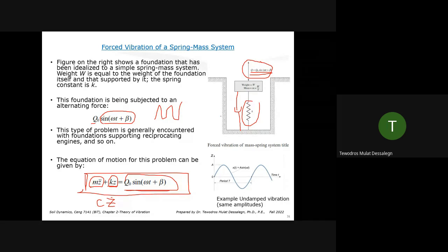In the material assumption, if you assume both damping and stiffness, then you'll have both forces, the damping component and the stiffness component. When you analyze a static problem, it's always the stiffness component, which is K times Z equals the force. But for a dynamic, general equation of motion, we have three: inertial, damping, and stiffness components. And depending on the force we have, sometimes one is 0.